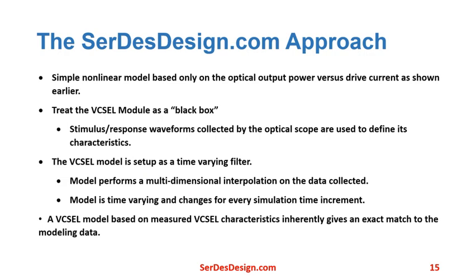The SerDesDesign.com approach for modeling the VCSEL module is different. It's to treat the VCSEL, with its driver, as a black box with stimulus response waveforms used to define its characteristic. The VCSEL module was based on the data collected by the optical scope with typical characteristics shown earlier. The measured VCSEL characteristics were provided by Reflex Photonics.